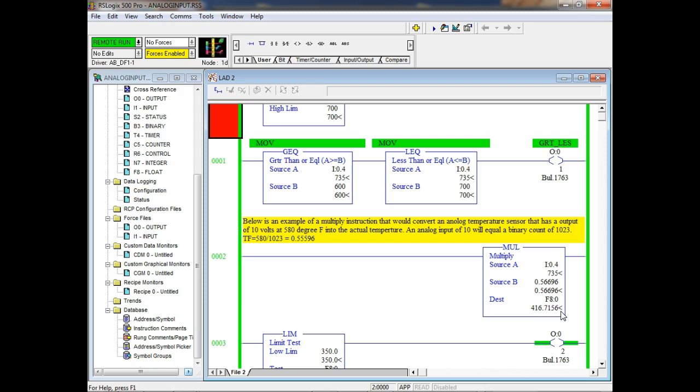So this is a 10-bit DAC. The 1200 over there has a 14-bit DAC on it. So that sucker has a lot better resolution, right? 2 to the 14th minus 1 would be the maximum count. So what we have to understand on A to D, we're going to get a binary number that represents an analog quantity. The more bits you use in the binary number, the better the resolution. Resolution is a term we use for accuracy. The more accurate it is.